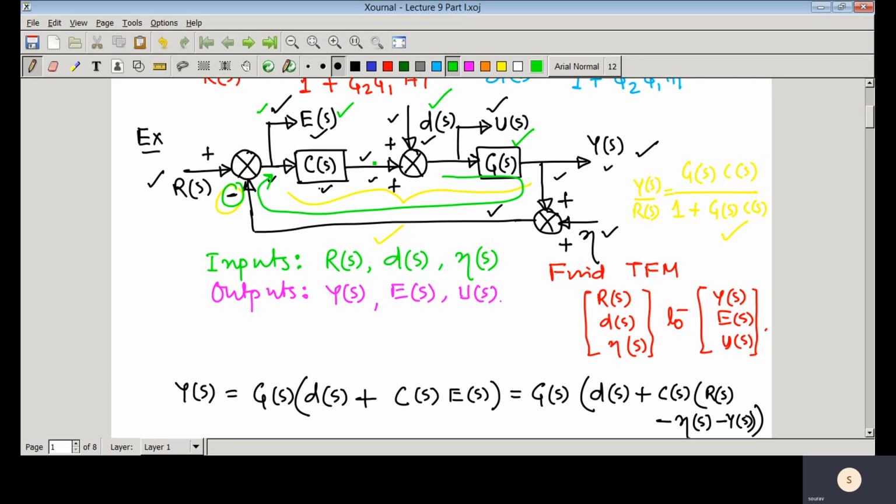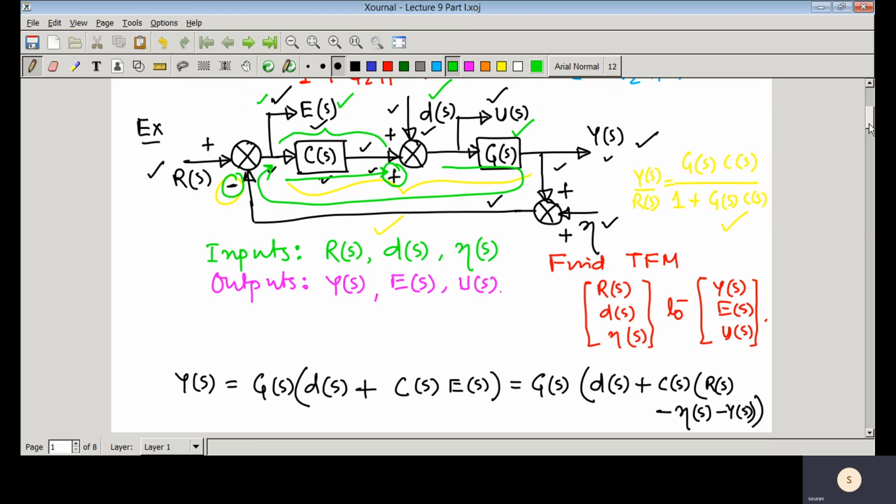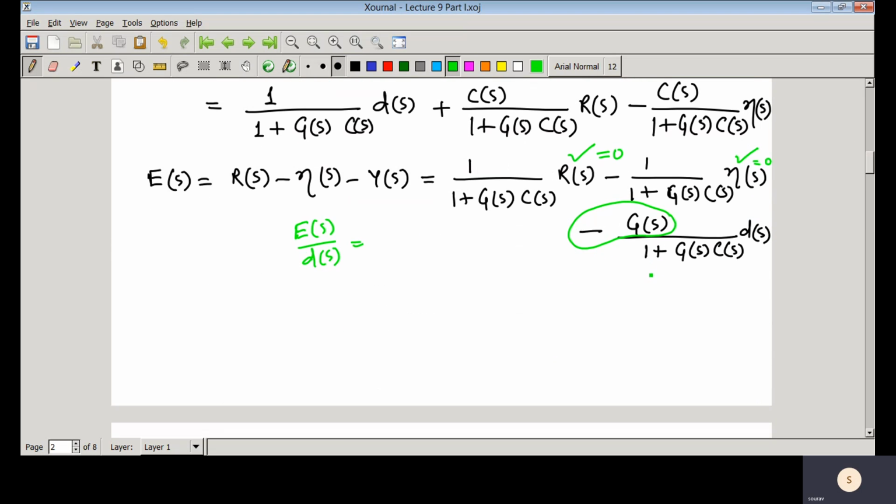Then you can see that this portion, from here to here, is the feedback path, and here you can see that it is using positive feedback. Now if it is positive feedback, basically it would be 1 minus, and as the forward path transfer function is minus GS, then minus minus would be plus.